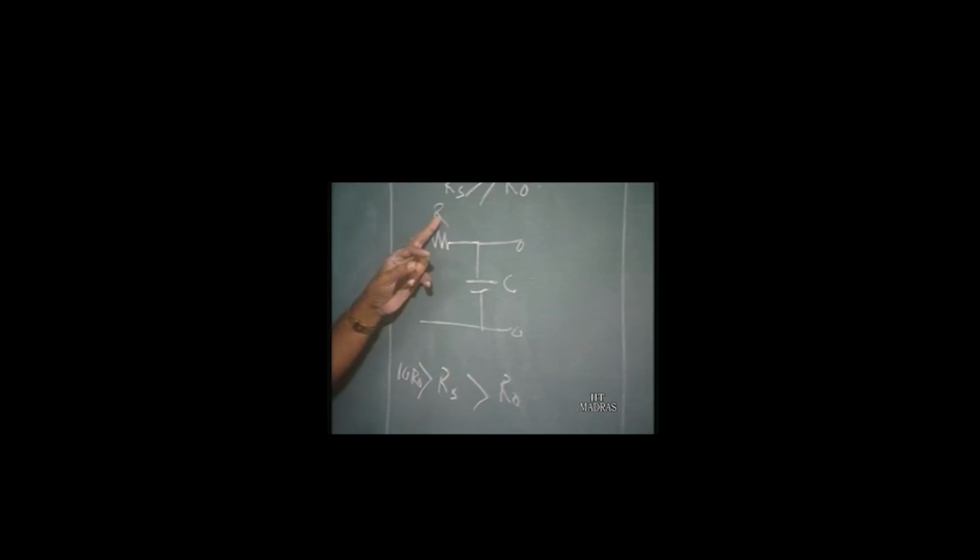This is the resistance of the line, this is the total capacitance of the line. But this type of model does not give very correct results, because we know that the resistance and capacitances are distributed, but this is using lumped values. So what is done is a 3-section pi model is generally used, which is given like this.